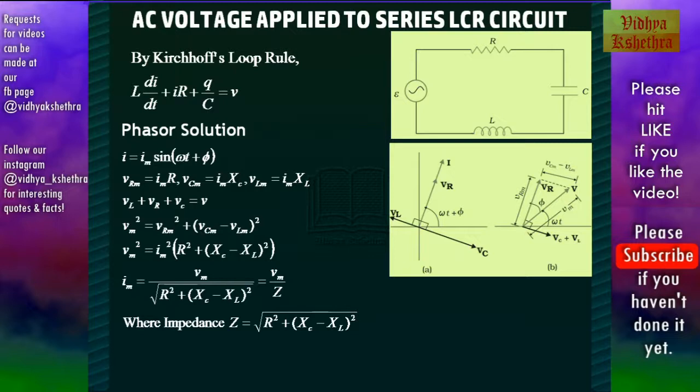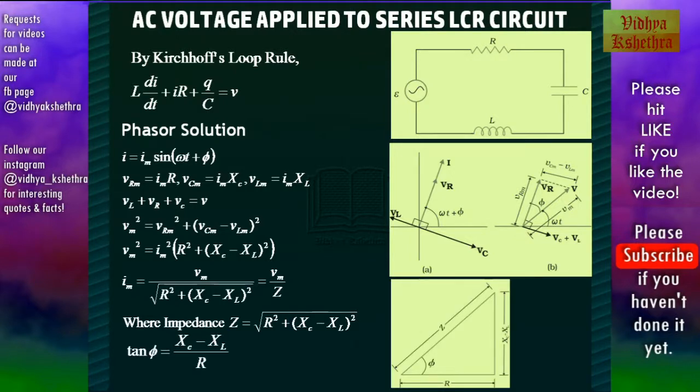If the LCR circuit is inductive, that is, if XL is greater than XC, then the current lags the voltage by phase phi. And if the LCR circuit is capacitive, that is, XC greater than XL, then the current leads the voltage by phase phi. Now, from figure B, we can obtain the impedance triangle. And from that, we can write tan phi is equal to (XC minus XL) by R, so phi is tan inverse of (XC minus XL) by R.